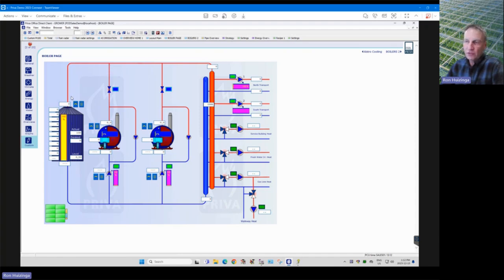So the 90 Celsius will fill the tank and push the cold water at the bottom of the tank down, and it will come back into the boiler, be heated up by the boiler, and make a loop like this. So we keep filling layers of 90 degrees. If all the layers are filled up with 90 degrees, then that buffer tank is considered 100% full of heat. If the tank is completely empty, which means it has all the return water from the greenhouse through all the sensors, then that determines it's empty.